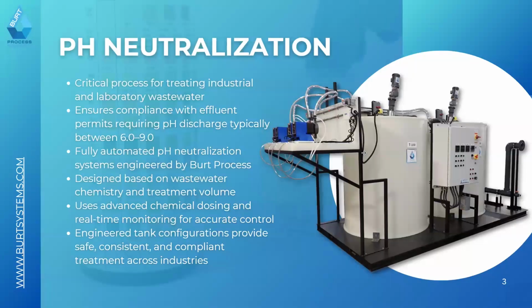facilities. pH neutralization is the fundamental one. Whether you're talking about CIP waste, CIP 100, 200, 300, citric acid, phosphoric acid, or potassium hydroxide, it's just used to wash down process kettles or other areas. They have an impact on the pH, both in the caustic as well as in the acidic direction. Certain processes in the pharmaceutical industry can generate waste as high as 13 to 13 and a half when using extensive cleaners. Obviously, the push toward single use has helped mitigate some of the water requirements for the system, but it's still an integral part of any system.